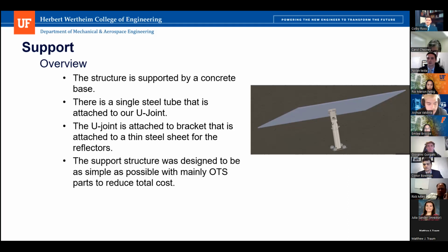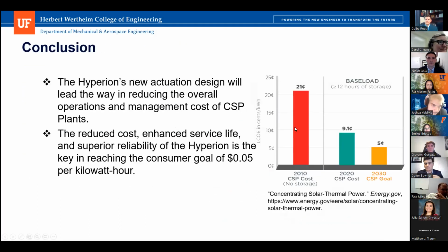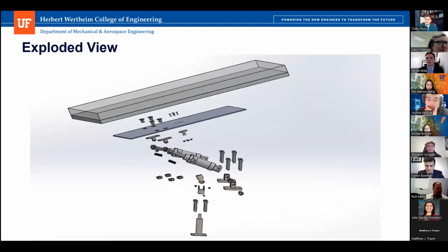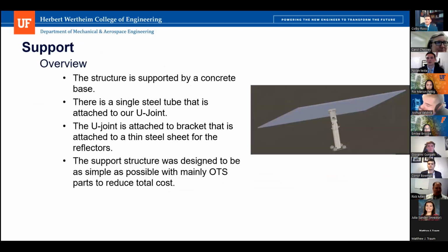Okay, so again, when you're providing structural analysis, you need a free body so that the person looking at it understands exactly what it is that you're analyzing. I thought that might be what you were doing, but I can't tell that just by looking at the equations, because you just give me a force value, and I'm not sure where that force value is coming from. We have that calculated in our appendix, which is a hidden slide, but he can go and show you that. No, I don't need to see it. I'm just saying, when you present to people, the key thing to any structural analysis is to always start with free bodies. Yes, sir. That makes sense.